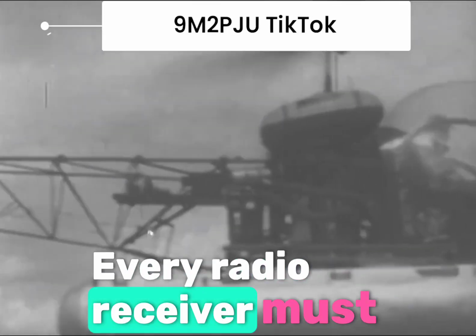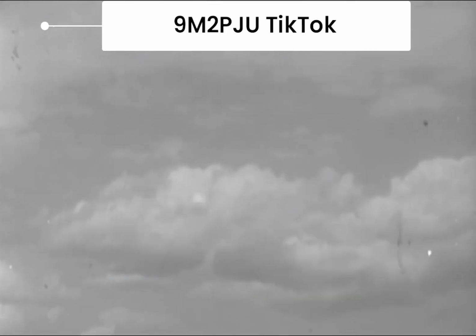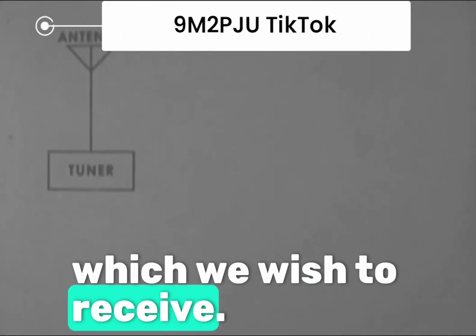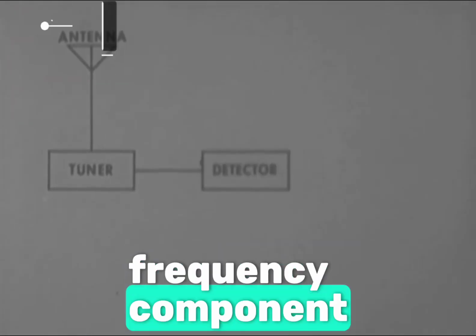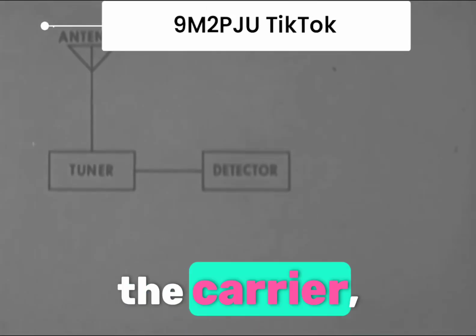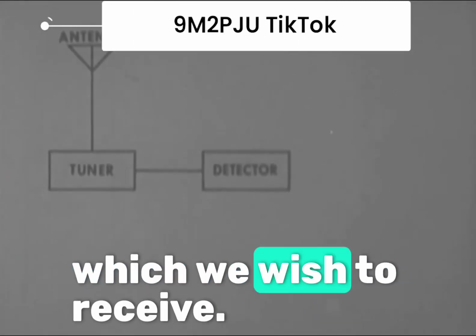Every radio receiver must have an antenna in order to pick the signals out of the air, and a tuner to select the one frequency which we wish to receive. The selected signal is passed into the detector, which separates the high-frequency component from the low-frequency component. The high frequency is the carrier, while the low-frequency component is the message which we wish to receive.